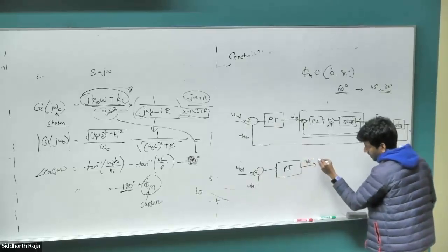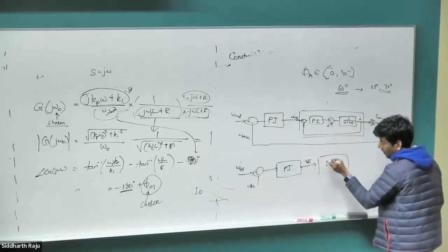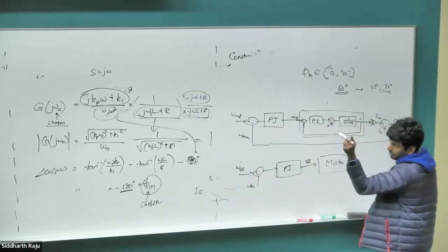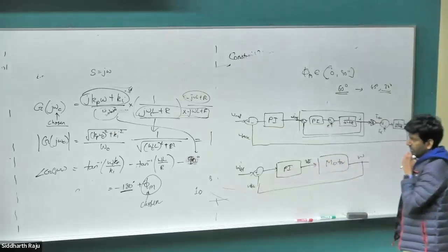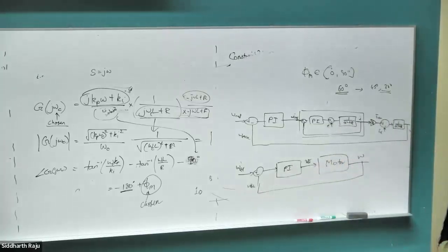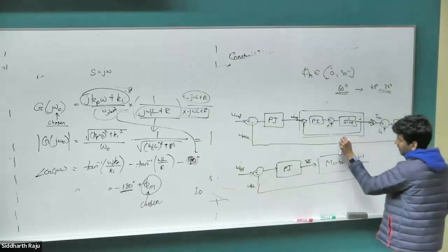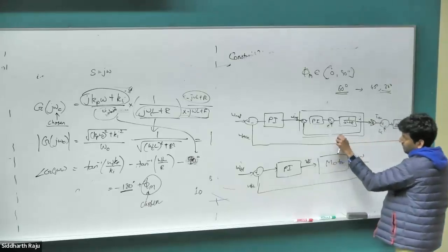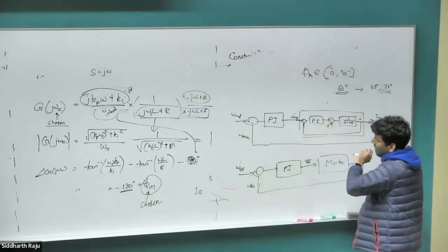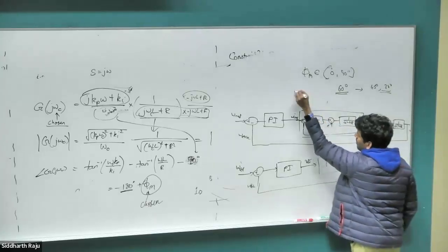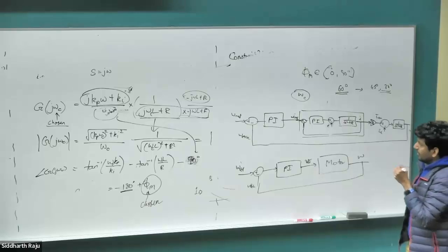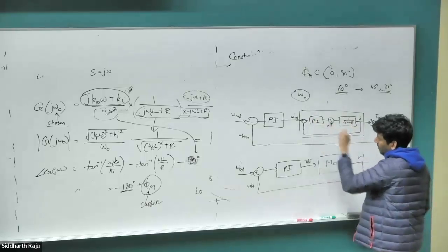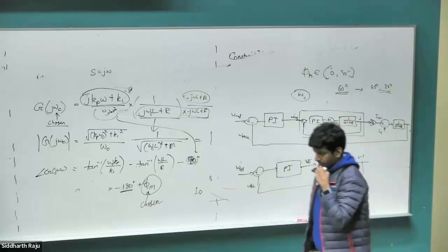Both of them are okay. One is preferred over the other. And this goes into our full motor model, the complicated, big one, which I drew. And then omega comes out at the output. So this is also fine. Either way we can do it. But there is a big advantage with doing this. Let's say that this system that I've designed has a bandwidth, or basically the crossover frequency omega, that is very large. Then what, in control system terms, can I equivalently model it as?